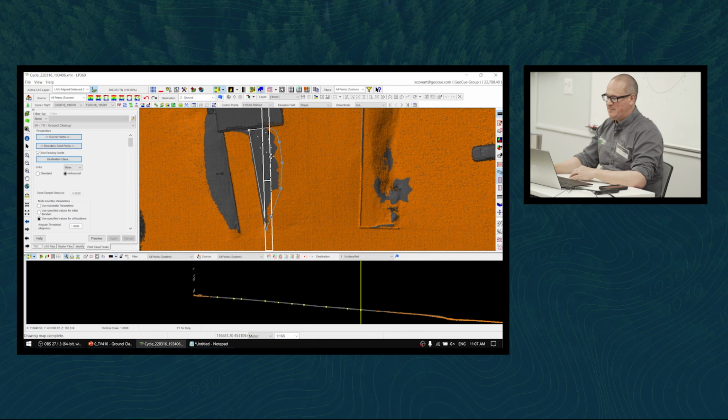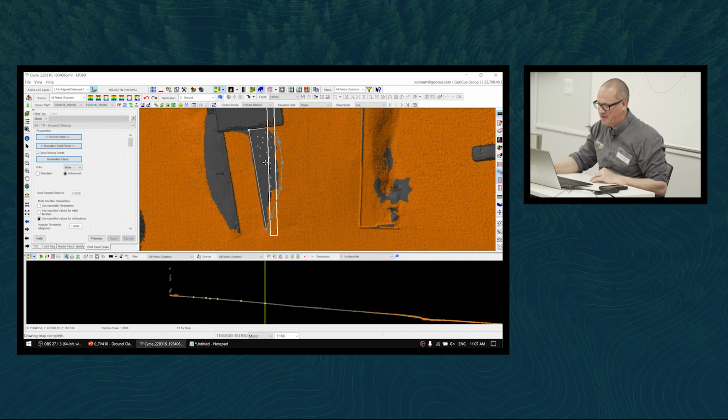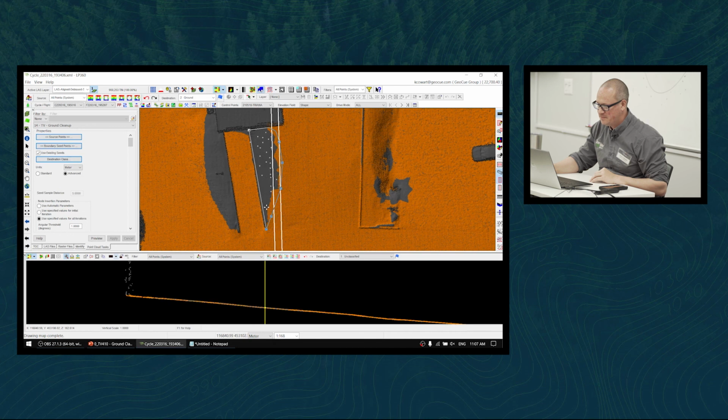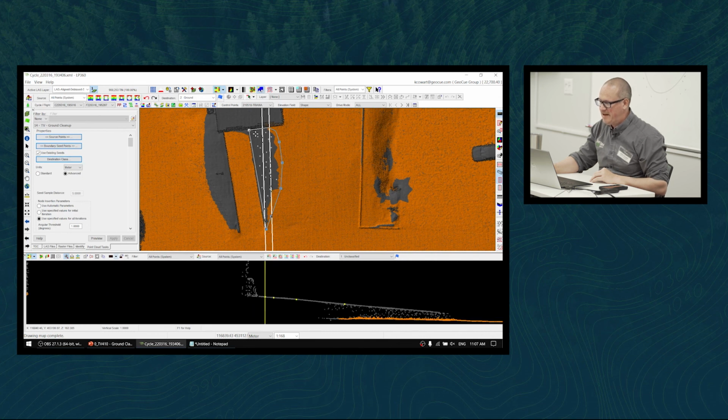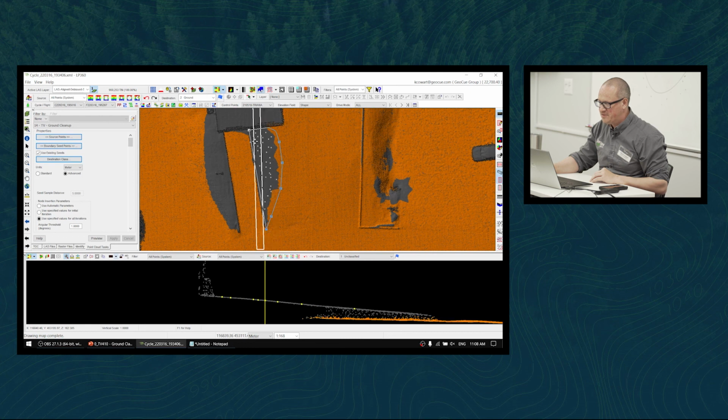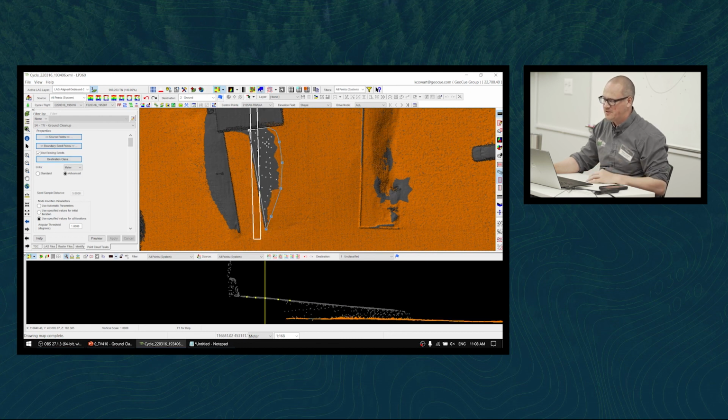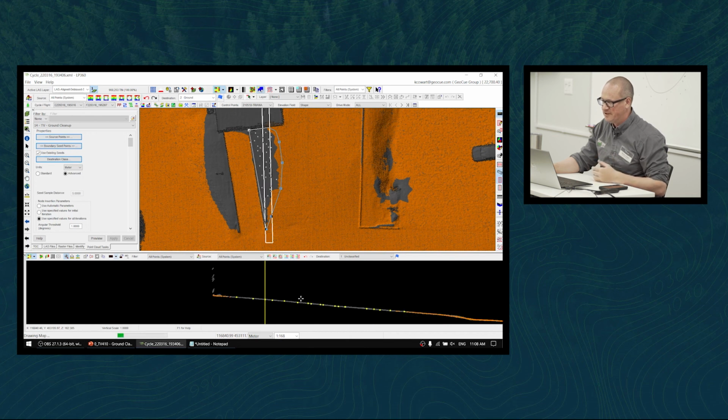With these seed points, you don't have to go too crazy and do like 500 of them. The more important thing is to have an equal distribution. You want to cover the whole area with a nice even distribution of points. So I'm going to go through there like this. Spread them out well, and make sure that they're all actually on the ground. When I'm happy with my seed points and their distribution, to apply the changes for this point cloud task, I'm going to double click the final point and you'll watch it update. There we go. So it cleaned up the ground.